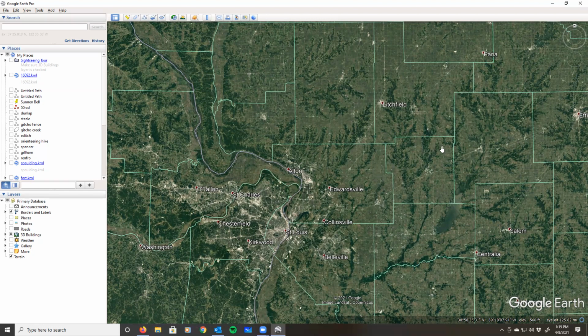The central meridian would run also through the center of the county, but what you would find is that on the east side of this central meridian, the convergence would go to the east, whereas on the west side of that, the convergence would go to the west.